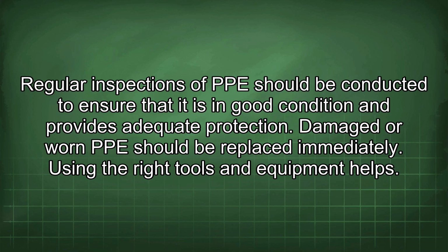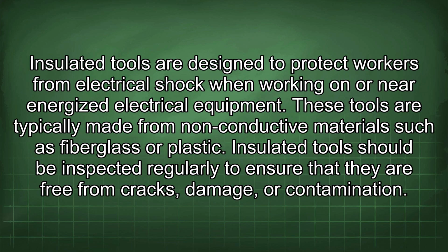Using the right tools and equipment helps. Insulated tools are designed to protect workers from electrical shock when working on or near energized electrical equipment. These tools are typically made from non-conductive materials such as fiberglass or plastic. Insulated tools should be inspected regularly to ensure that they are free from cracks, damage, or contamination.